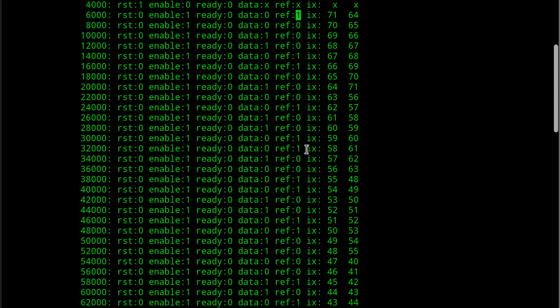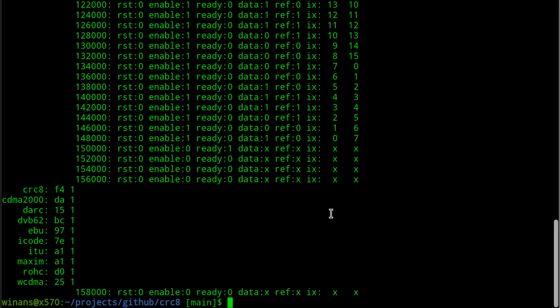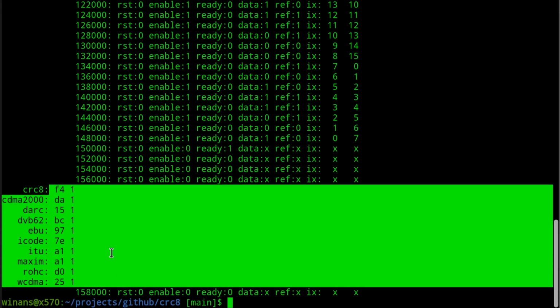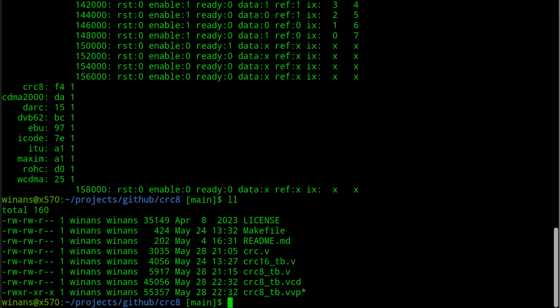And this is done on a byte basis because that's the width of all of the test data because we're sending ASCII. All right. Now, as you saw, all these get checked against what they're supposed to be, and it'll print a 1 on the right if it's got the right value. Otherwise, it'll print a 0. So these all checked out based on me instantiating it right, me sending the data out in the right order or reflected order, and all this other fun stuff. Okay? Which is pretty cool. I was very happy once this thing started working.